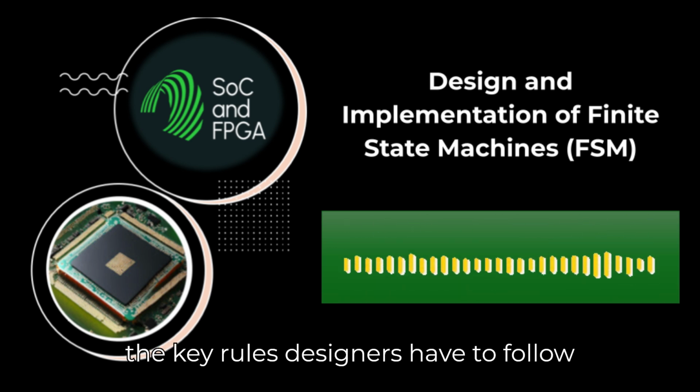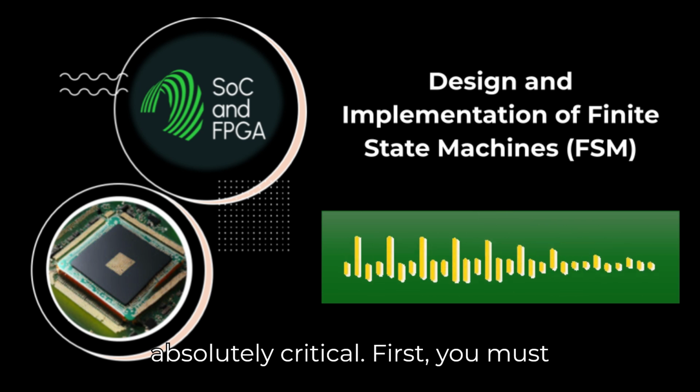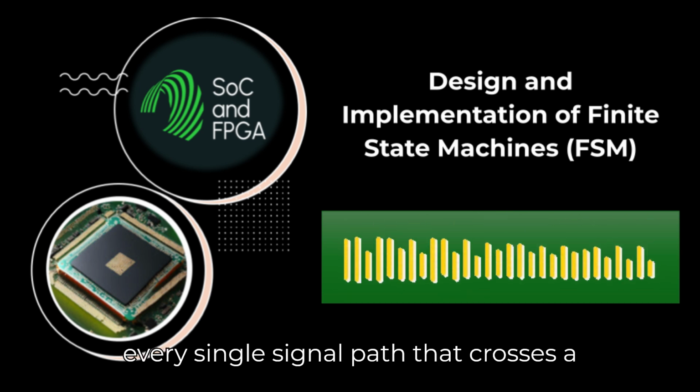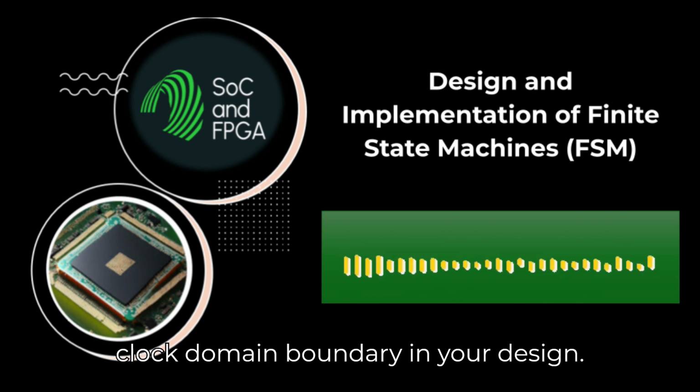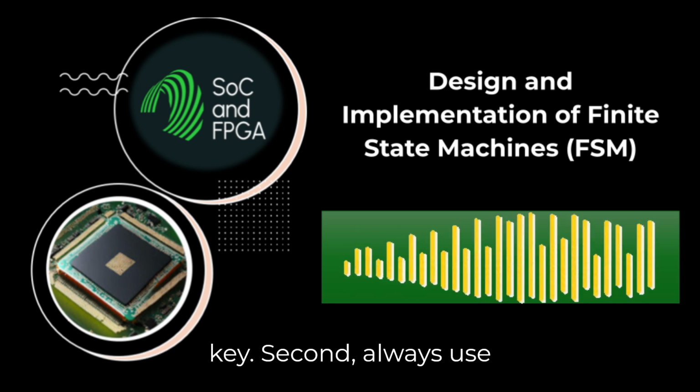So what are the key rules designers have to follow when dealing with CDC? Discipline is absolutely critical. First, you must clearly identify and properly constrain every single signal path that crosses a clock domain boundary in your design. Tools can help, but designer intent is key.